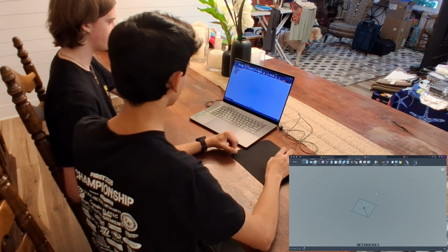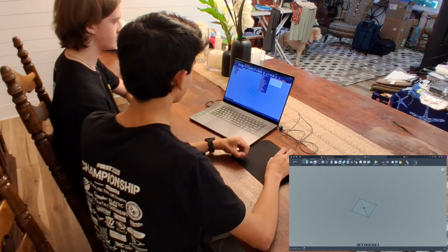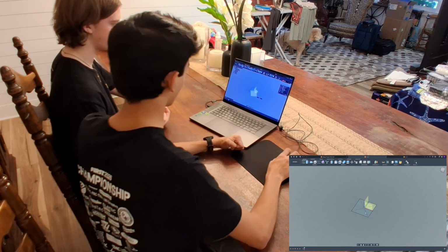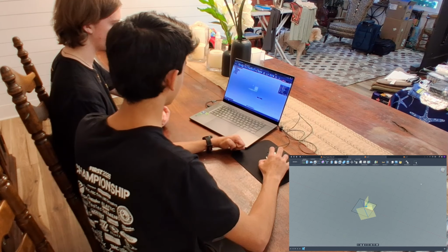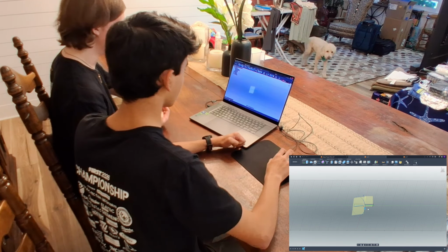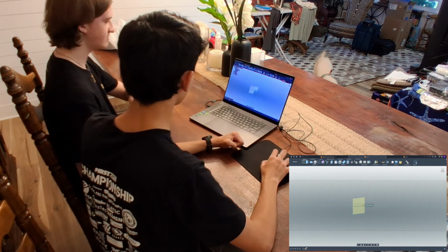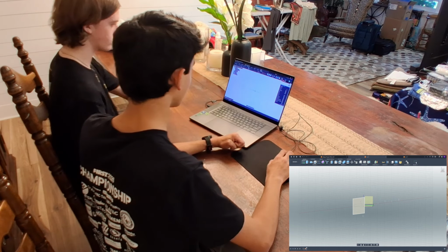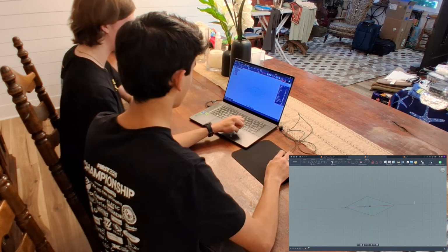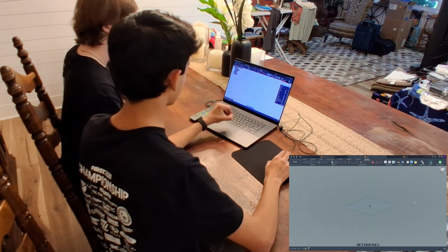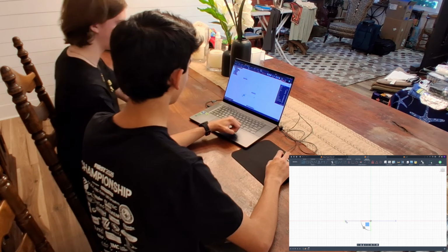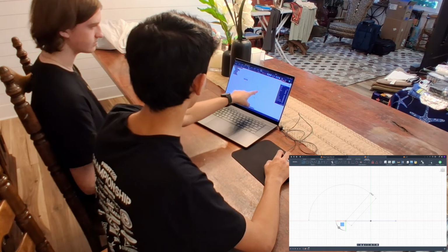We're going to start with the offset plane here, or plane at an angle actually, and then use that diagonal we made. Come up 90 degrees here. And then from here we're just going to form a triangle. So we're going to take a sketch on that new plane we formed. Make sure you project that line you made, and then figure out how high this line needs to be to have that 1 inch, and it'll also be at the center.